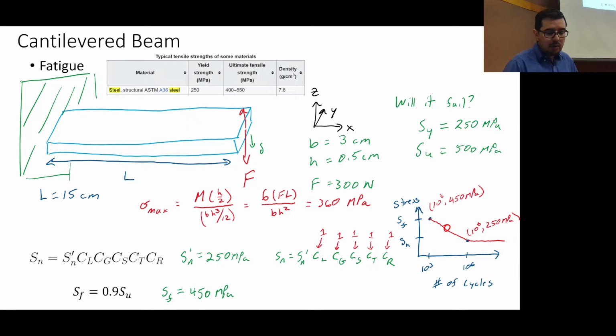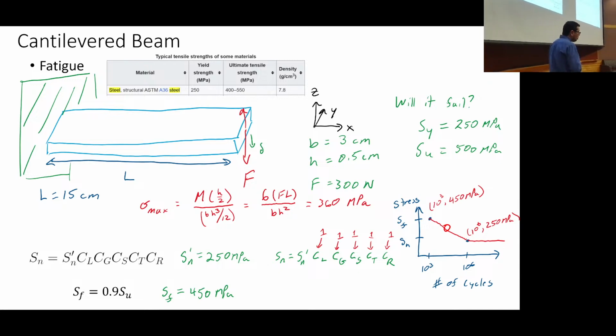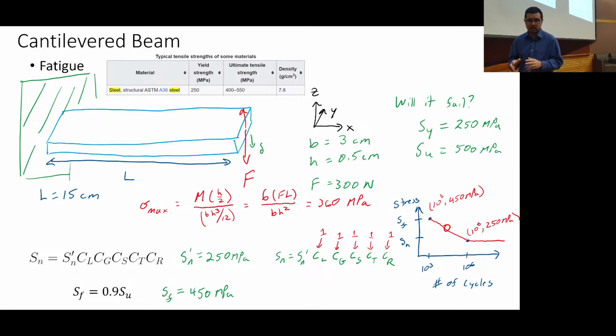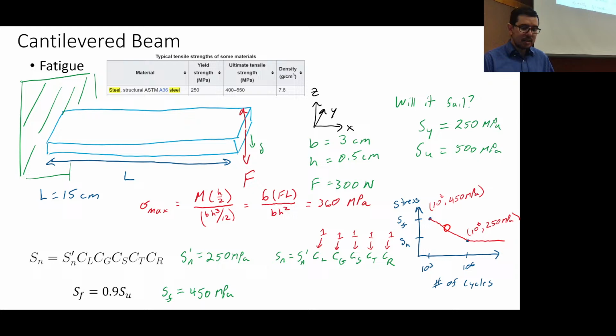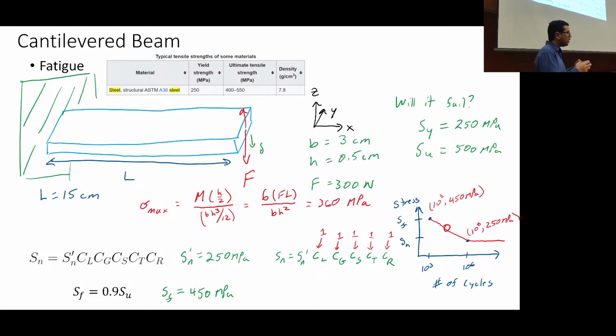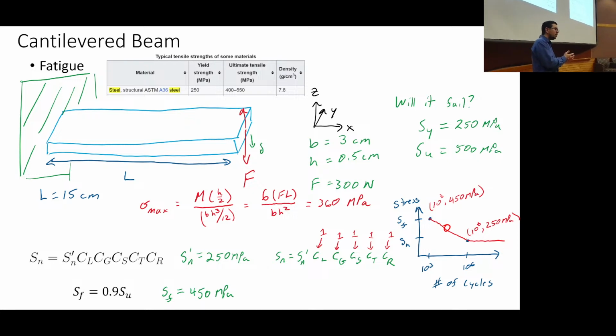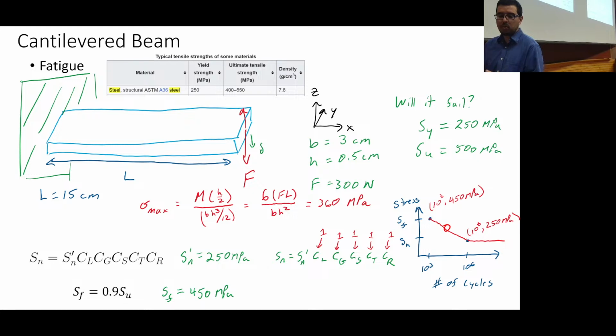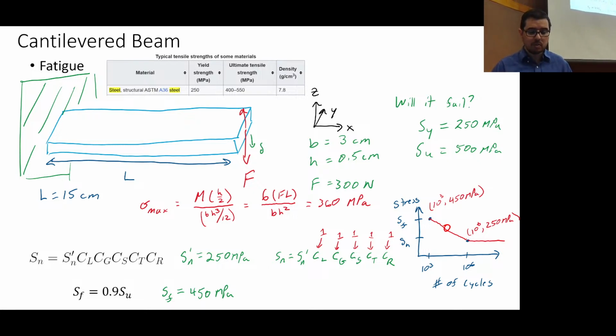So, how do we go about running this type of situation in ANSYS? Well, we can plug in those components, which we already did for the S-N curve, and have ANSYS predict, based on the normal stresses involved, or the Tresca, or the equivalent von Mises stresses, whether or not we're going to have failure after a certain number of cycles, or how many cycles we will last with these different loadings.